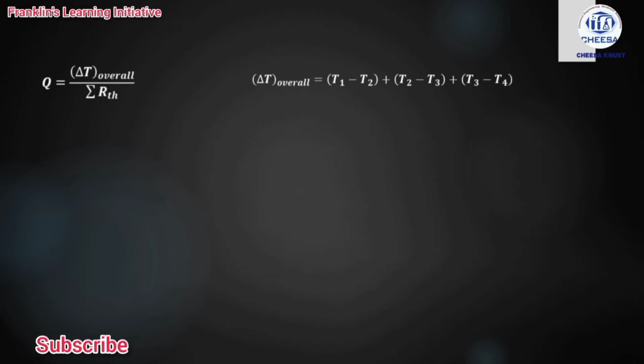So we can see that we can do some cancellations. Minus T2 cancels plus T2, and minus T3 cancels plus T3. In effect, the overall temperature difference is going to be T1 minus T4. That is the inner one minus the outer one. Putting in our values, the overall temperature difference is 540 degrees Celsius.